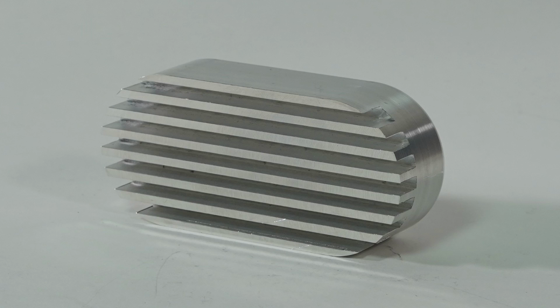Next feature up are grooves. Grooves have similar limitations of pockets, and they can simply be thought as narrow, deep pockets. Grooves are commonly used when a narrow throughway is required for parts to interlock, create a negative space for running electronics, or for gaskets to sit in.